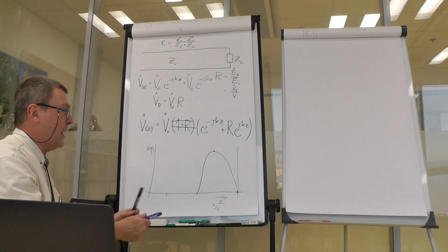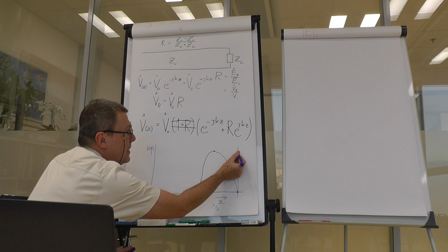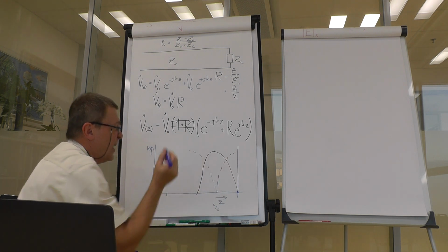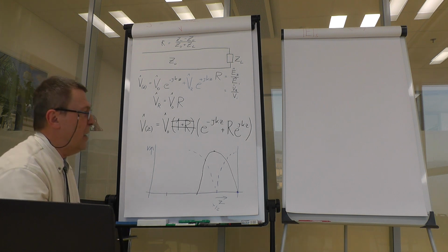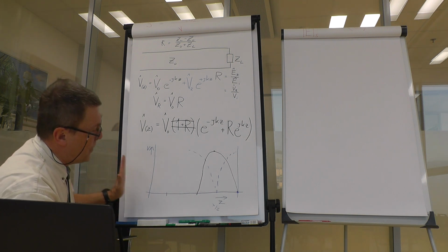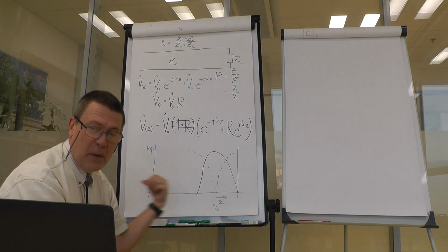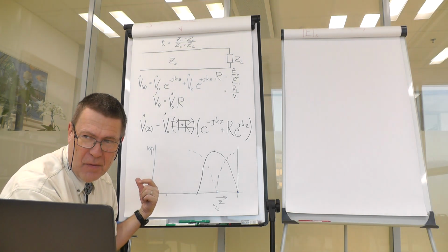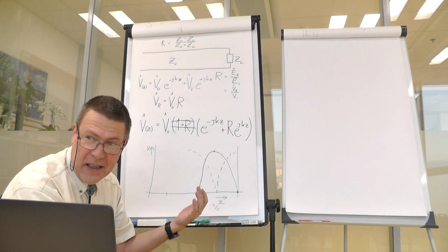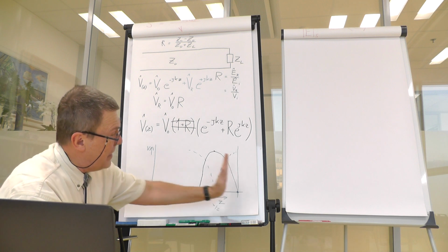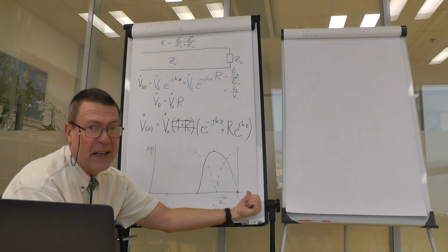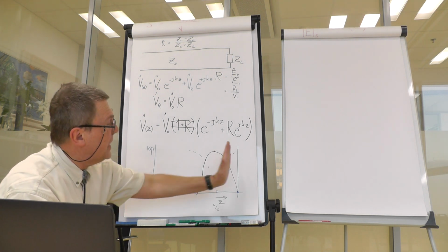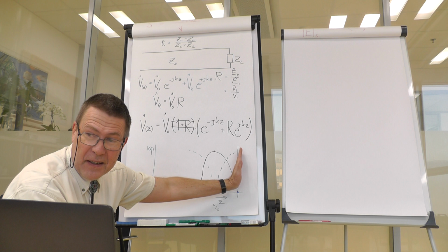So the magnetic field would turn into this shape. And we will have two waves, one going there, one going back, and each of them carries the same average power over the line. So the wave carries the power there, it reflects and carries the power back, the same power. So we have no power in the terminating impedance.